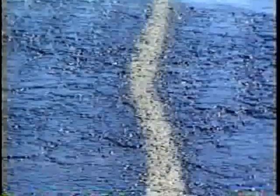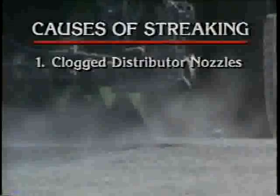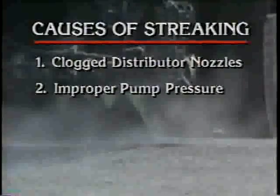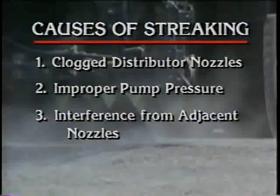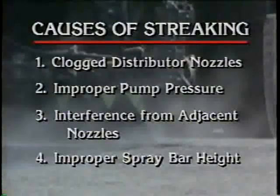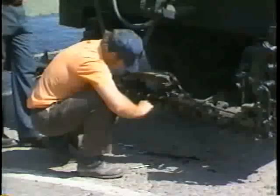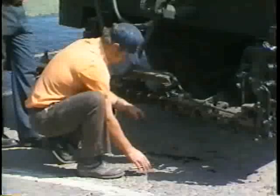The most common problem associated with improper asphalt distribution is streaking. Streaking is caused by one or a combination of the following conditions: clogged distributor nozzles, improper pump pressure, interference from adjacent nozzles, or improper spray bar height. Monitor each of these conditions during the spraying operation and make adjustments as needed.